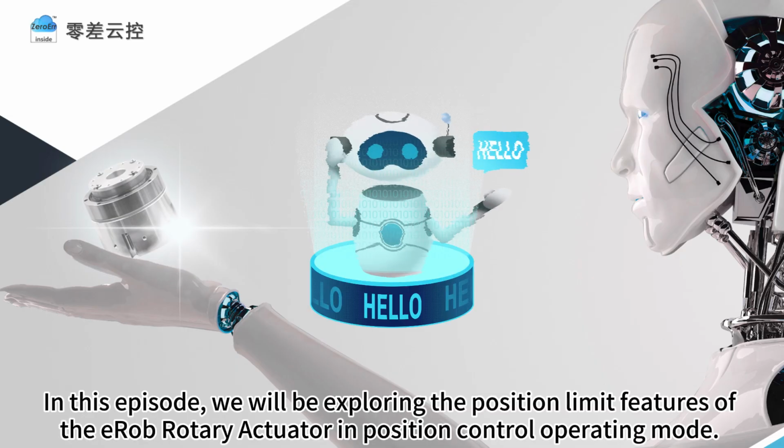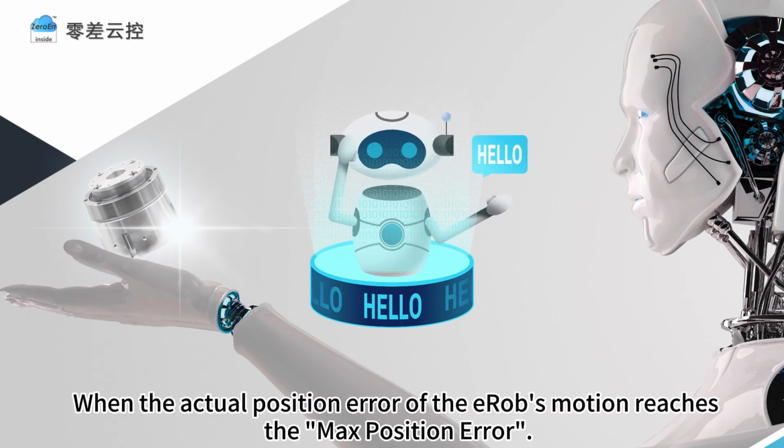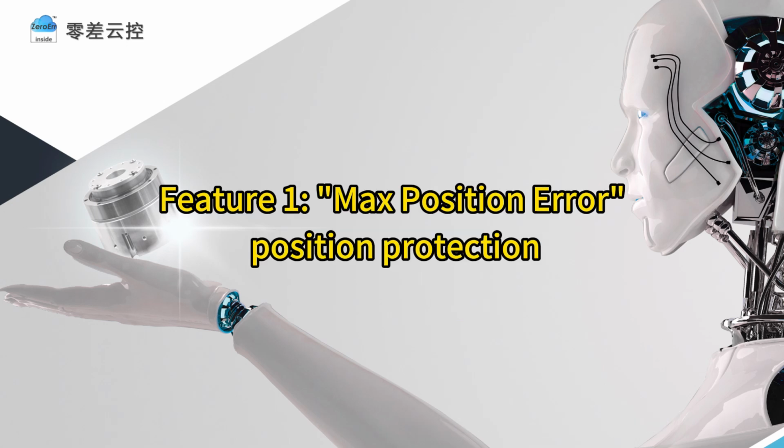In this episode, we will be exploring the position limit features of the eRob Rotary Actuator in position control operating mode. When the actual position error of the eRob's motion reaches the maximum position error, the rotary actuator will trigger an error and stop operation. Feature 1. Maximum position error position protection.